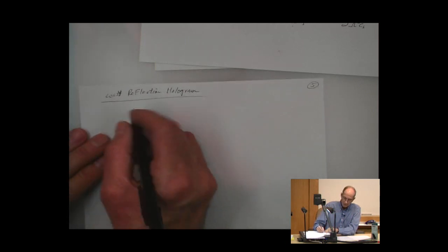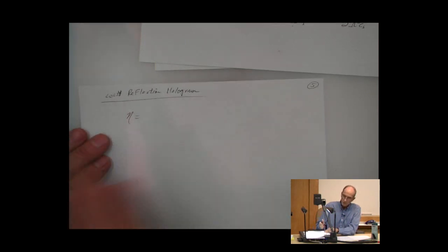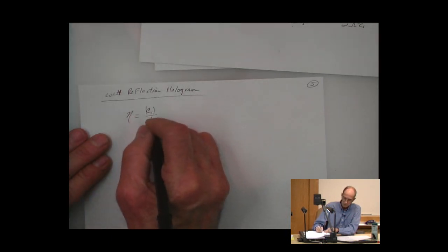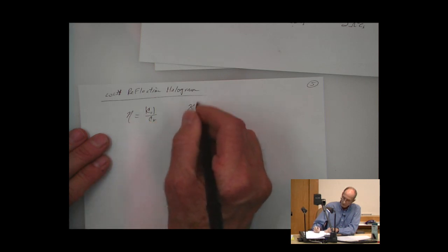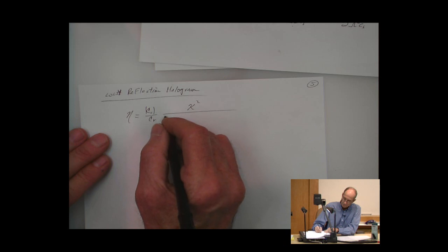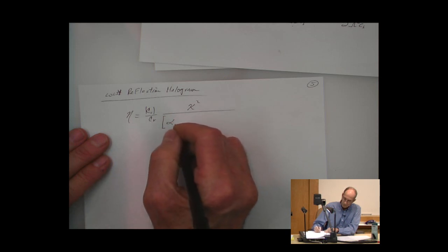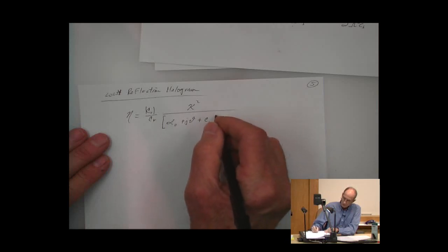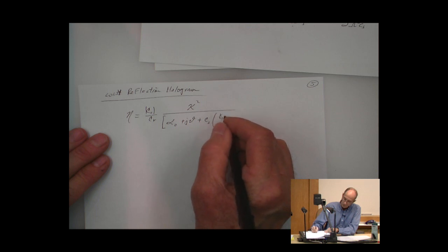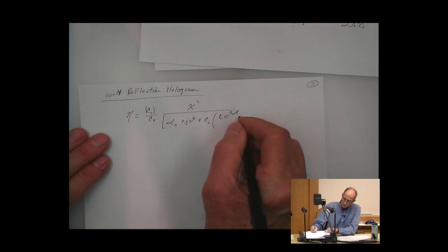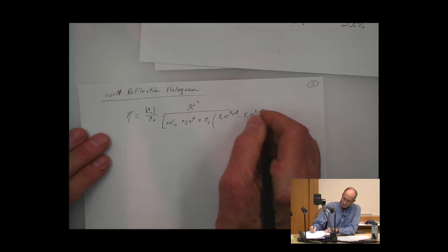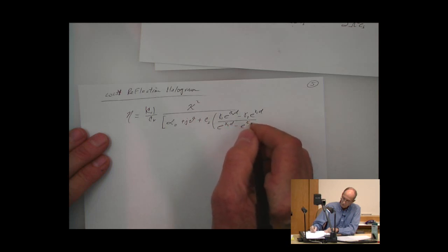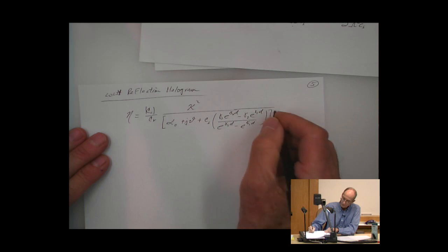But at any rate, what I usually do is just write a small computer program to use the general form, which is c sub s over c sub r times the coupling coefficient over alpha 0 plus j times our detuning parameter plus c sub s times gamma 1 e to the gamma 2 d minus gamma 2 e to the gamma 1 d over e to the gamma 2 d minus e to the gamma 1 d. And all of that squared.